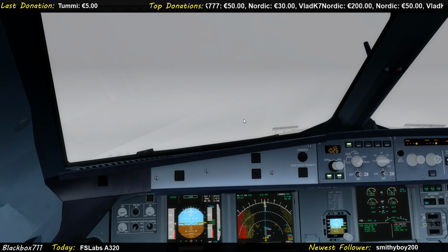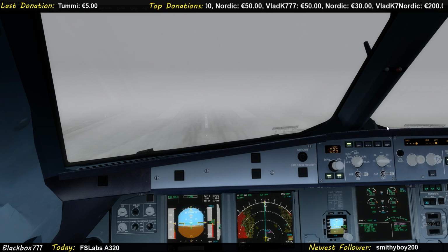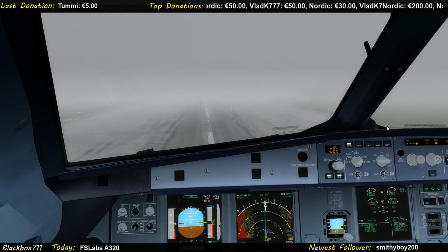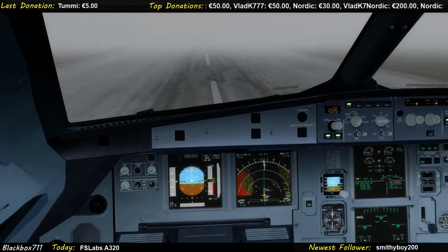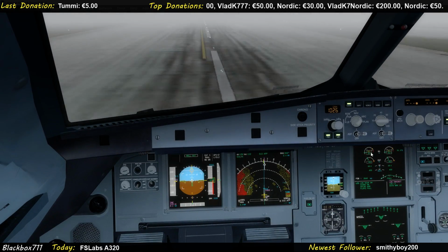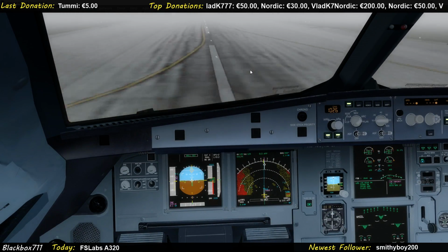So full concentration, guys. Have a look out of the window here with me. It's very foggy. 200. No contact yet. 100. Still no contact. 50, there you go. 40. Runway lights in sight. 30. 20. 10. Retard. Thrust levels idle. Spoilers. Reverse green and decel.